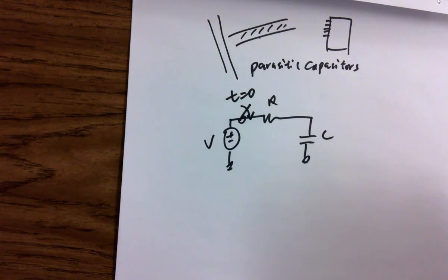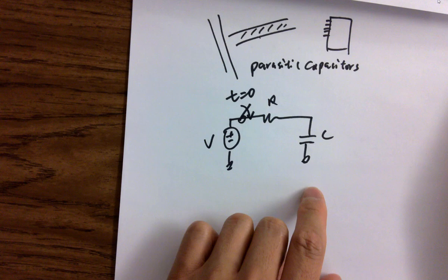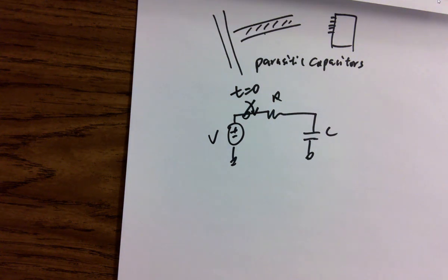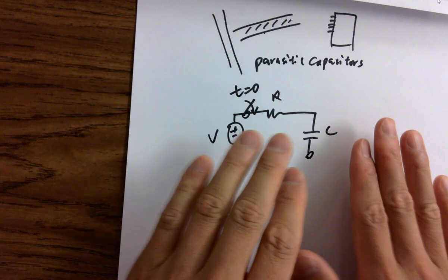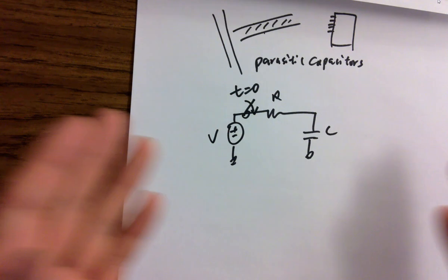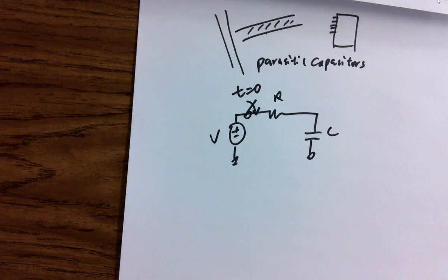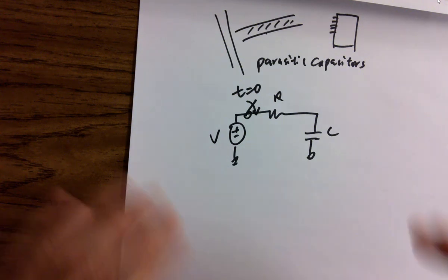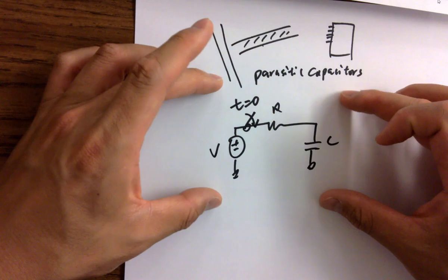So in general, for digital circuits, we are not assuming any initial voltage being stored at the capacitor. The capacitor, you can imagine from the name, has a capacity. It's actually storing charges. Even though we don't want charges to be stored in the capacitor, it does store charges. This can be treated as a model for all the parasitic resistance and capacitors of the digital circuits, either on the PCB or in the chip. So eventually you got a model like this.